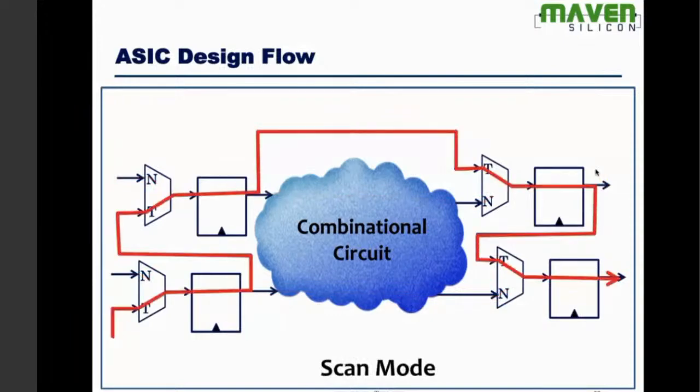this is called scan chain. I want to skip the combinational logic and I want to connect all the flip-flops like a shift register. So what I'm going to do is, during test mode, I'm going to inject a stream of bits, and then I'm going to check whether the same stream of bits comes through the output. If it happens, there are no short circuits within the chip. This is very useful later on to find out whether there are any fabrication faults within the chip.